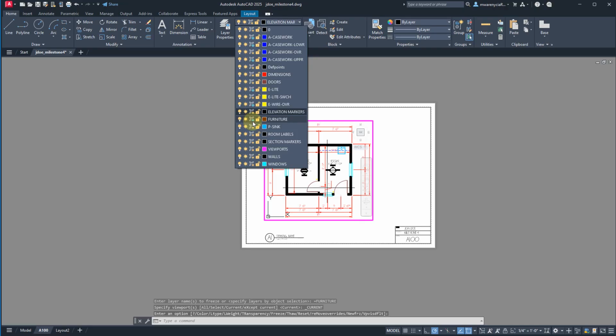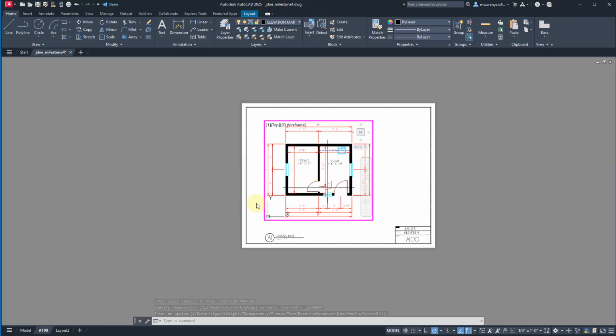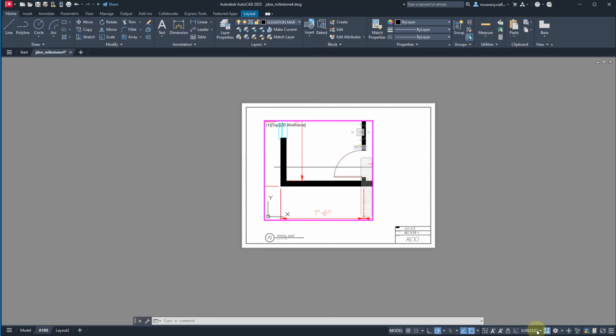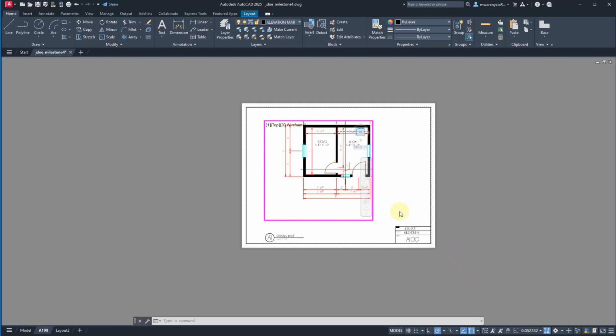We're going to do furniture on a different layer, elevations in a different drawing. We don't need the sink. We are going to want the room labels and dimensions is basically all we want. Oh, actually, sorry. We should show sections in here. Okay. So that makes that, and then set it back to 1/4 inch.